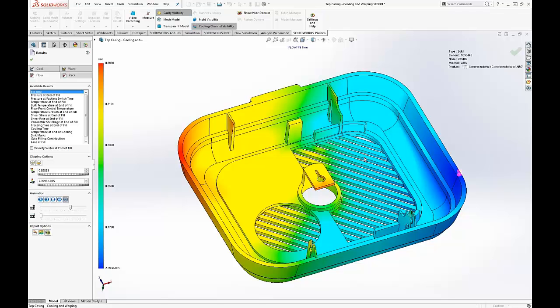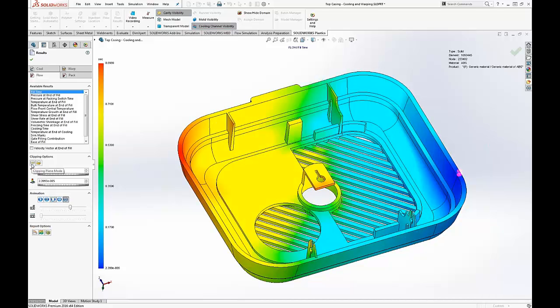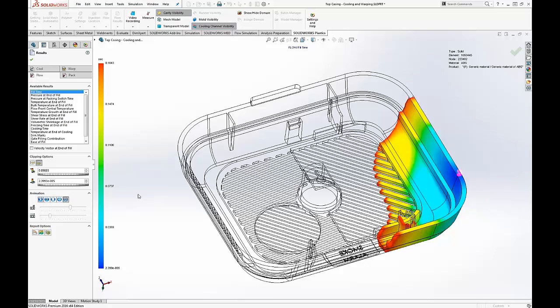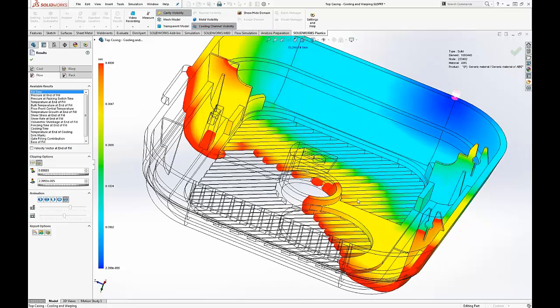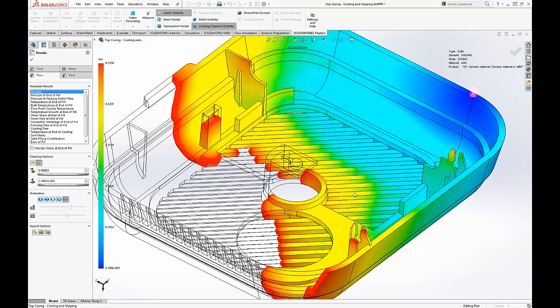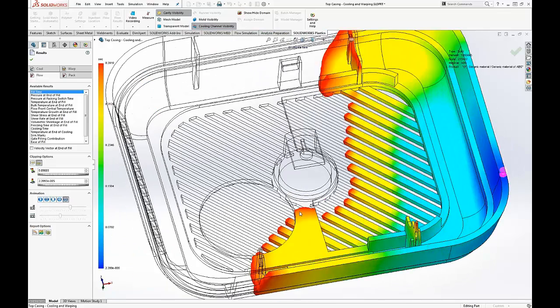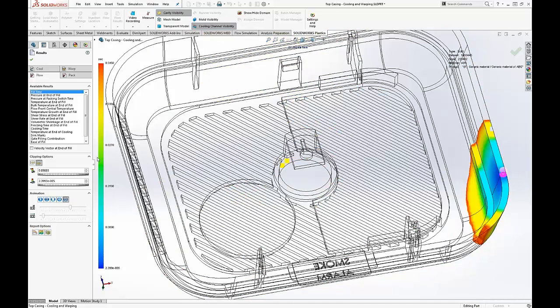Why? Because in this case we have a solid mesh, so it's far more precise and detailed. So in this case, I can show you the same results as before, but smoother. But also it's nice because I can see inside the mesh, because it's solid. So when I use this representation, you can see inside. So this is the effect of using a solid mesh instead of a shell one. Okay, and it's far more evident also where the weld lines are forming, for example, here.